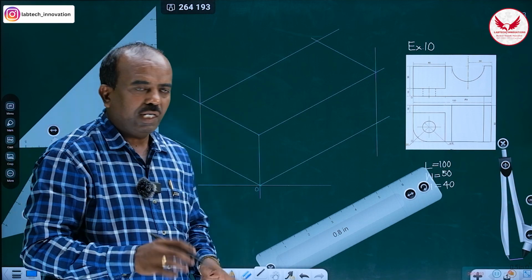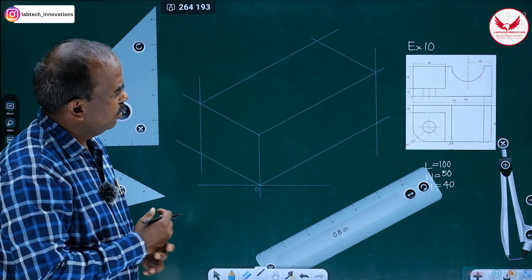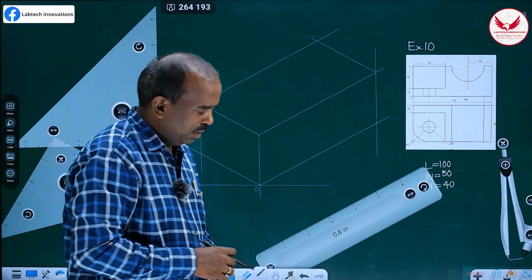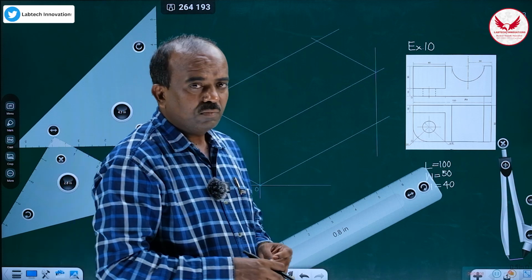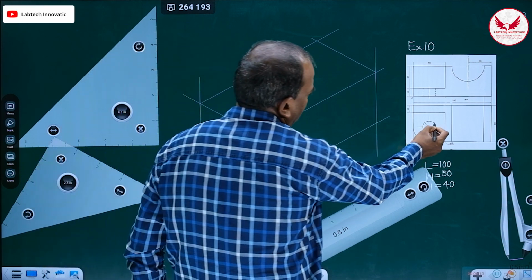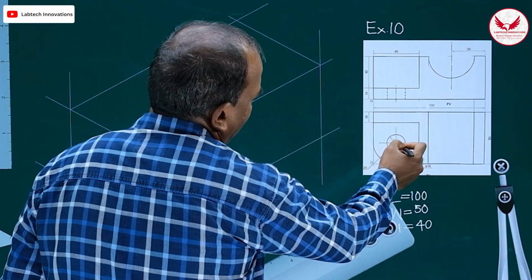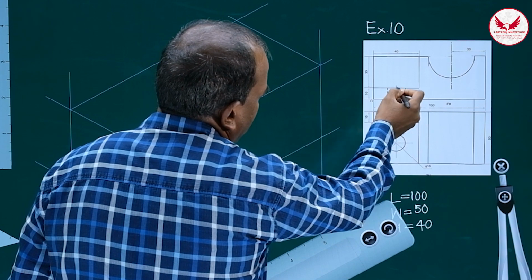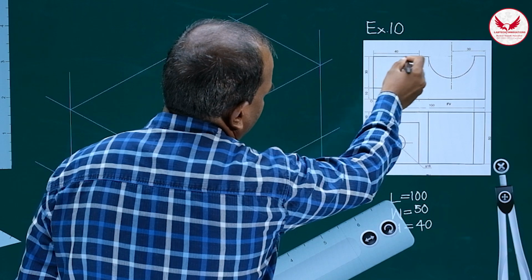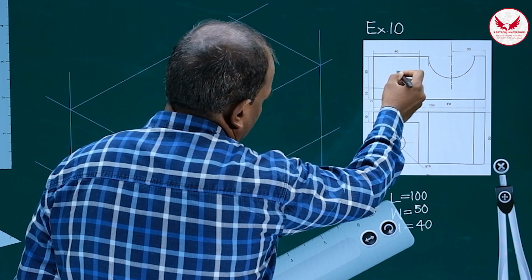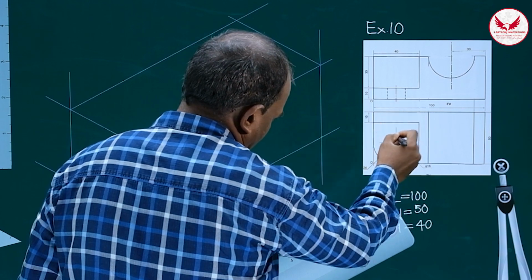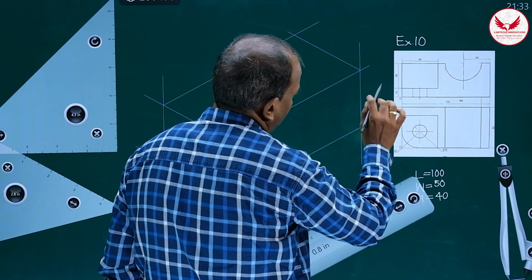Once we prepare the isometric box, after that what we have to do is analyze the problem carefully. And I always tell, when small holes are there, those holes help us. For example, this hole. Whatever this circular hole is there, it is at the height of 10 only, which means above this nothing is there. Above this portion, whatever is there is being cut. That's why this portion along with the circular hole is visible. So we get that hint.